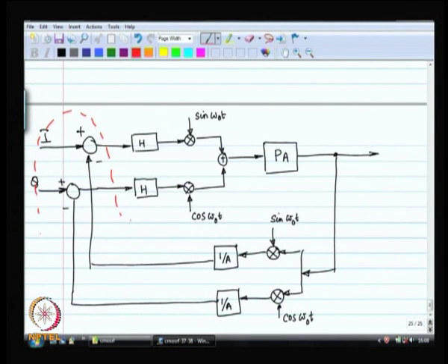So, it is feasible to make this entire block in the digital domain, okay, but you need 2 extra A to D converters, which may or may not be justified. So, over here what we need is some sort of an analog subtraction. It is not terribly difficult to make an analog subtractor at low frequencies.